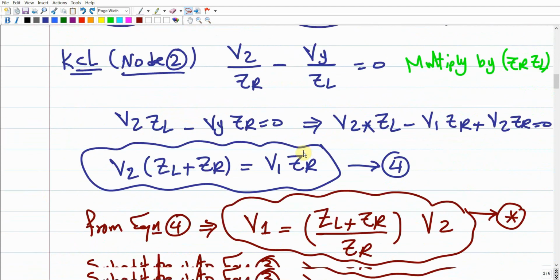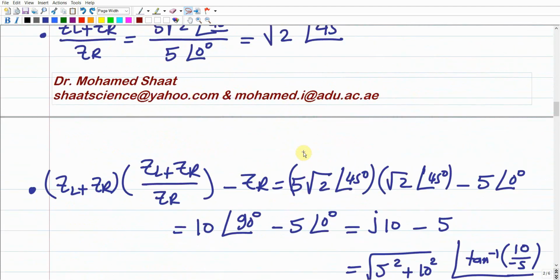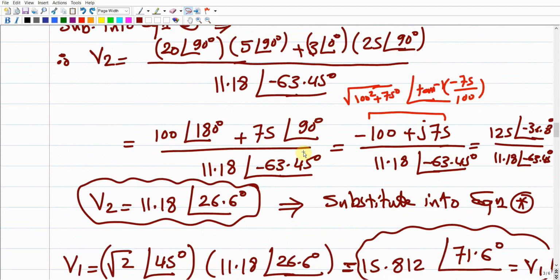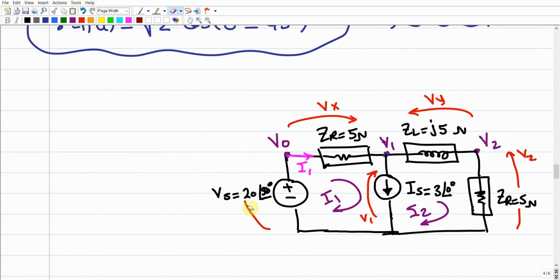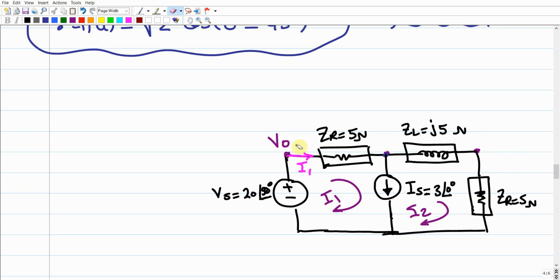So how can we do it? I'm just going to make a copy of this electrical circuit in the frequency domain. Since we're going to use the mesh current method, there should be no voltages here, right? These node voltages V1, V2, and V0 should be removed, right?